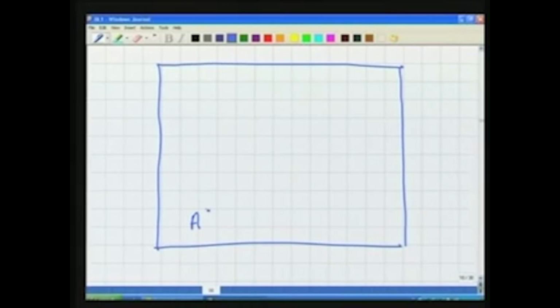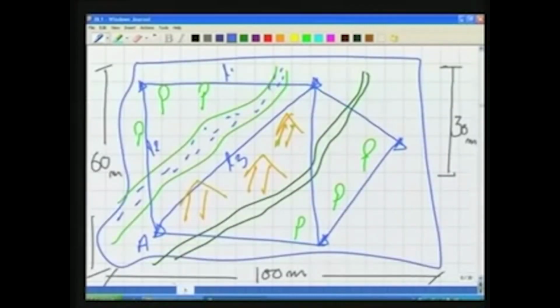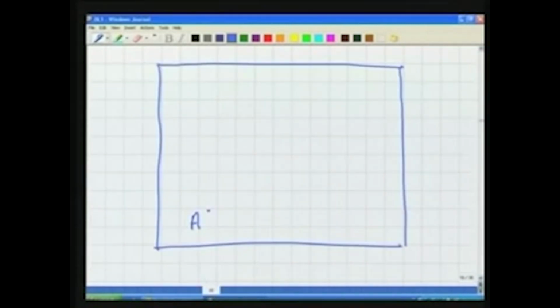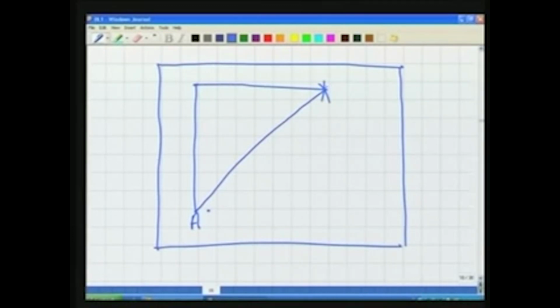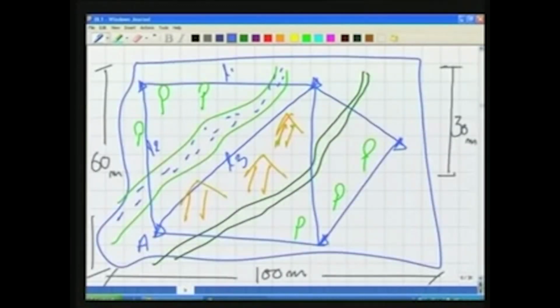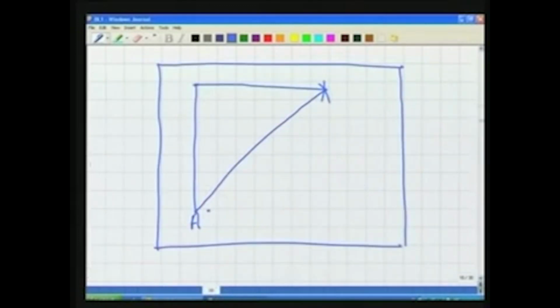Now, from A, as we had observed on the ground, we have lines going this way. So, what we do, we draw a line L3 and L2 and again from this point we take an arc. From A, let us say the very first line is drawn here, L1. We can measure the angle also, I am not talking about the angle now, and from here we can take the arcs of the rest 2 lengths. So, this point is fixed. Similarly, as per the triangulation figure there, we will draw the rest of the triangulation figure.